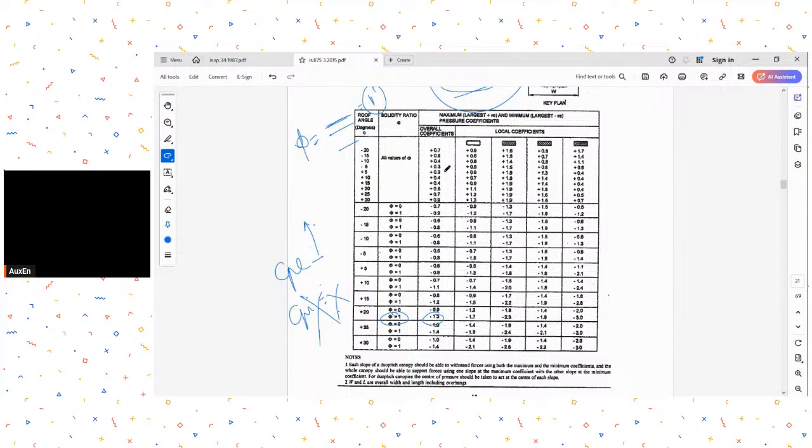All right. And then there is another case that you also need to consider. If this is my roof, CPE negative would mean acting away from the roof. So this will be case 1. For example, my roof is 20 degree, and for example, phi is 1.3. So you apply 1.3, 1.3. This becomes your case 1.